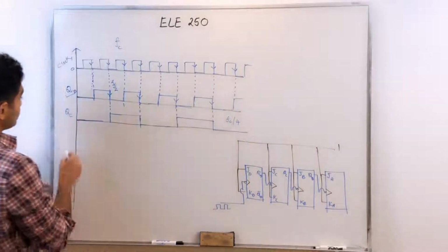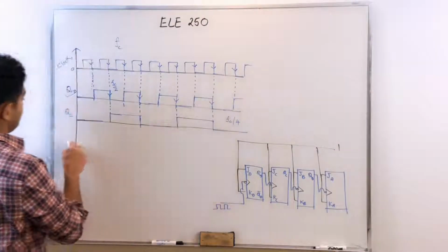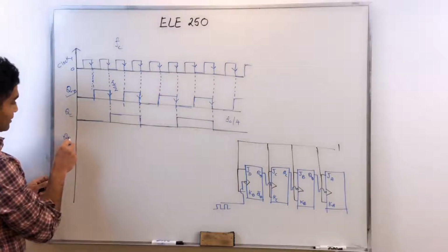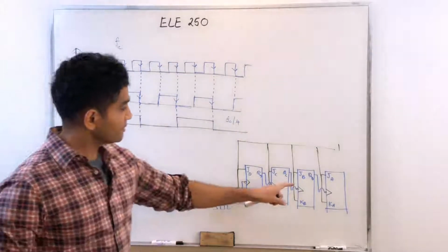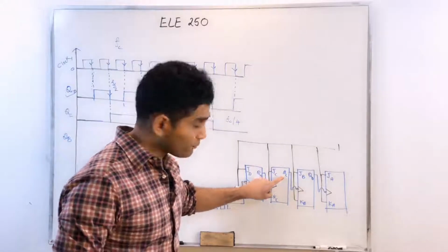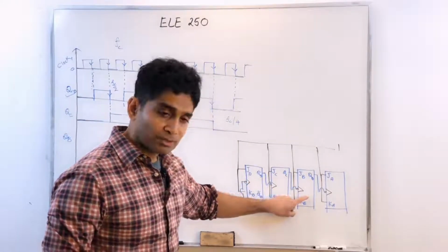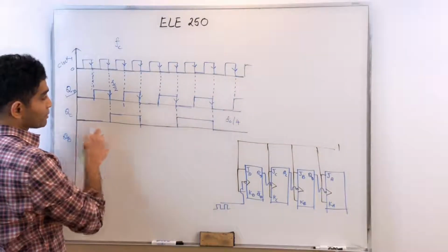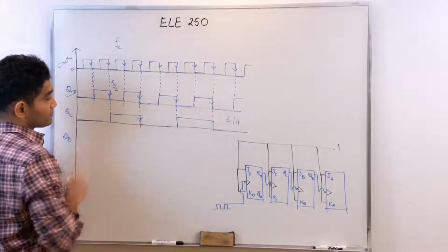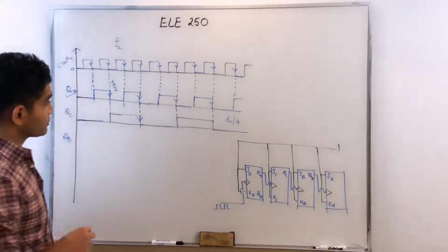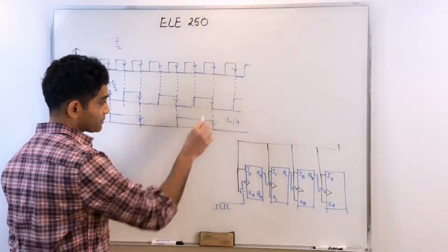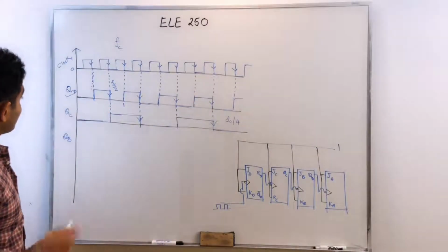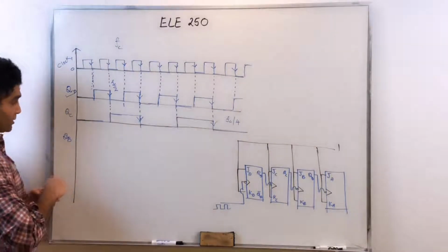Now let's do QB. Same discussion. The only difference here is I'm applying the output of QC as a clock to the JB flip-flop. So in this case, my QC becomes the clock, so those are my active edges. So I identify my active edges because that's a negative edge trigger flip-flop. Again, I assume QB to be 0 to start with.